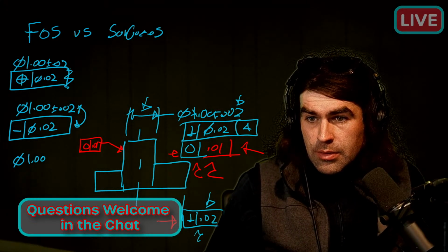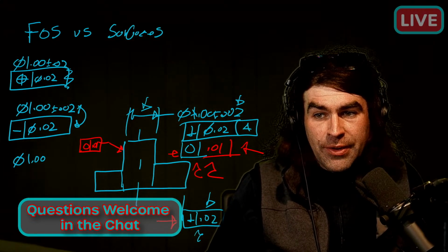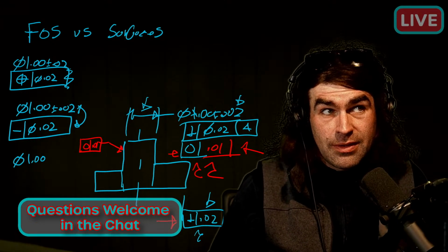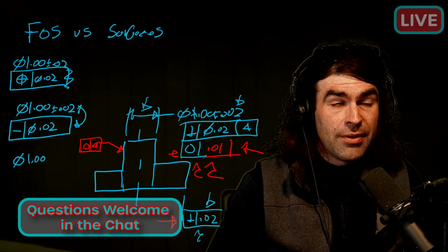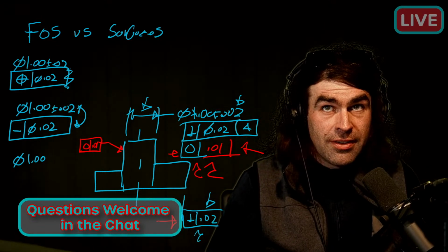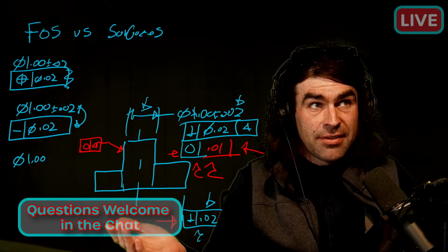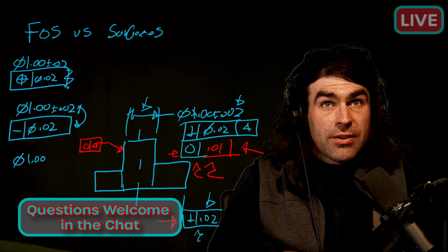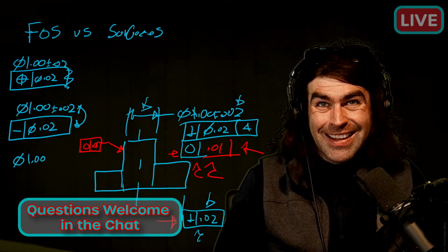When using SolidWorks MBD auto dimensioning, it automatically attaches a circular runout to the diameter. I don't want to disparage SolidWorks or anything, but I don't even know what they're doing. Whenever I try to use MBD, it gives me 500 decimal places, and it just does everything wrong. I don't want to say it's totally useless, but okay, you're saving people time by putting all of the wrong dimensions and stuff on there. So then I just got to go through and sort through it and delete everything and add it back again. So did it really do any good? Now, I don't know. Maybe I need to be educated on how it works, and I just don't understand. But the auto stuff doesn't seem to ever help.